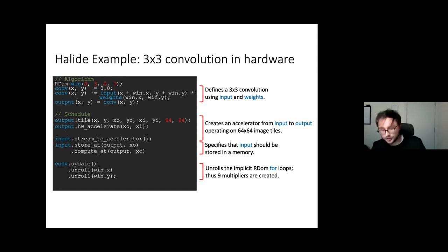expressing machine learning applications. And the really novel part of this domain-specific language is not the fact that you can easily express these functional stencil-like algorithms, but that it allows you to independently specify the schedule for the computational platform you are going to run on. So you might have a different schedule for running on a CPU or running on a GPU, or in our case, running on this CGRA accelerator.